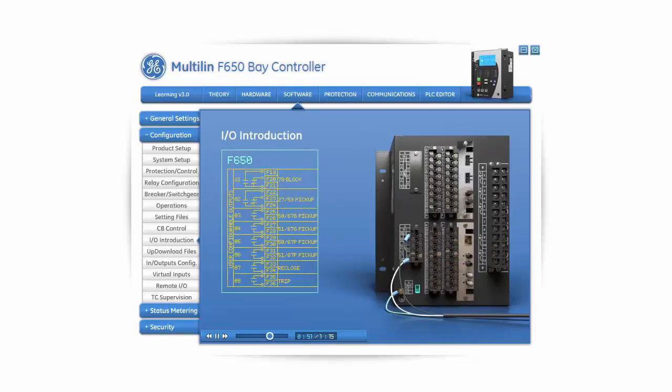Contact outputs. In the default relay configuration, the output contacts are organized to operate as shown. The 2 main output contacts are 07 and 08 on Board F, which are the close and open contacts respectively. The close contacts are associated to the auto-reclose function and the manual close command. The trip contact, 08, is associated with all protection functions that should be opening the circuit breaker. It is also activated by the manual opening command.